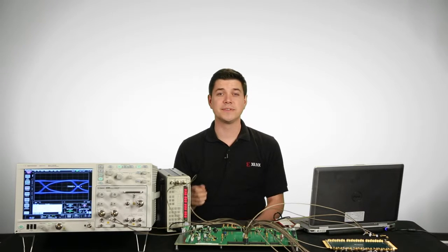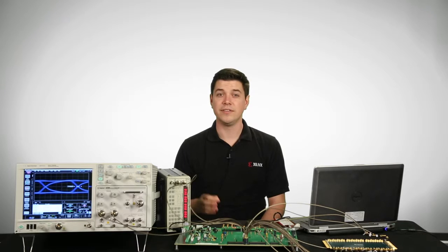In this video, we will demonstrate the Xilinx Artix-7 FPGA GTP transceiver, the industry's only transceiver in a low-end FPGA that offers auto-adaptive equalization, non-destructive 2D eye scan, and IBIS-AMI simulation models to simplify high-speed serial design.